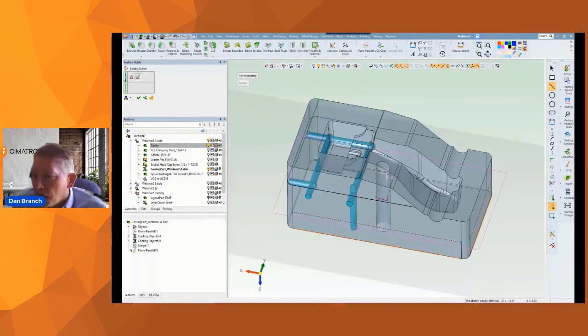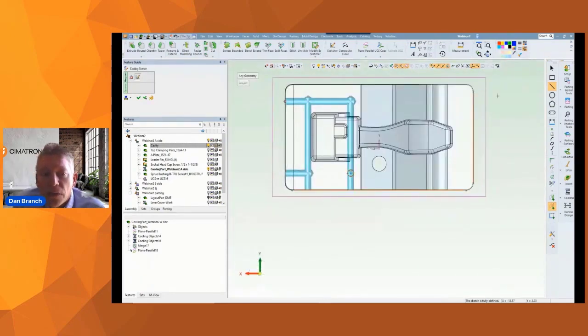I want to add another at a different depth, and I'm completely free to just sketch out whatever pathway I'm thinking of. The edges of the block or existing cooling holes can provide references that help me position these new lines. I do have some idea of the circuit I want at this level, so I'll draw it out here.